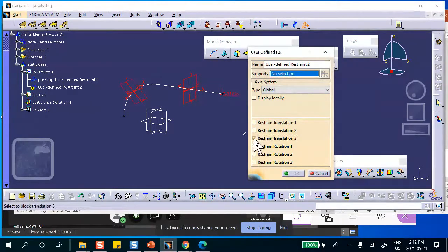If you can see the displacement, rotation is exactly the opposite. When this one is checked, you leave that one free. When these are not checked, you check them. That is the rule. Of course, it's this point that I'm taking. So this is the symmetry, for use of symmetry.